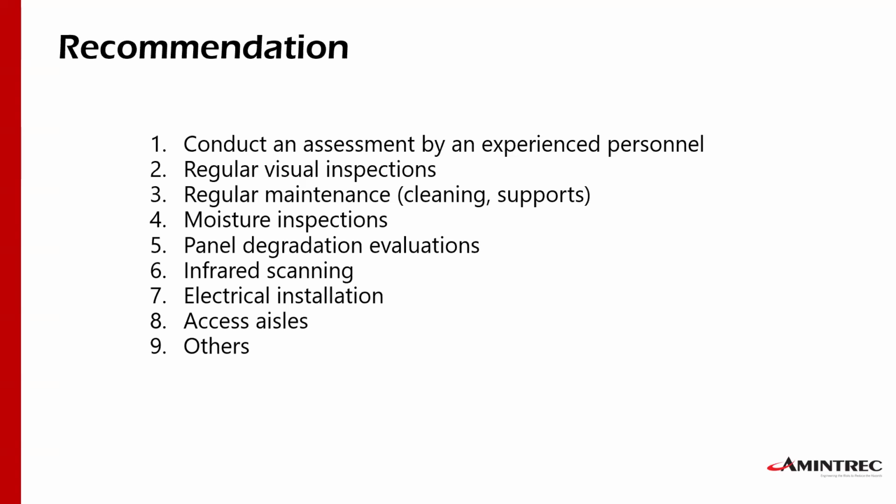And as you can see, if some panels are dirty, the other panels, not the dirty ones, when they're in the open circuit, those will heat up. If you have a closed circuit, the ones that are in the shade, under shading, those panels will heat up. Moisture inspection.